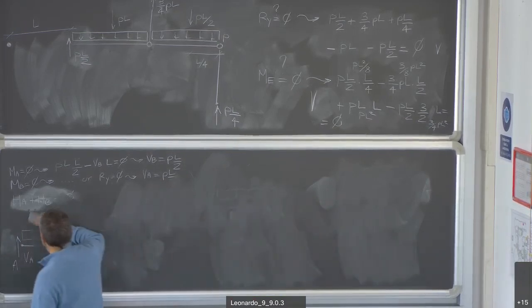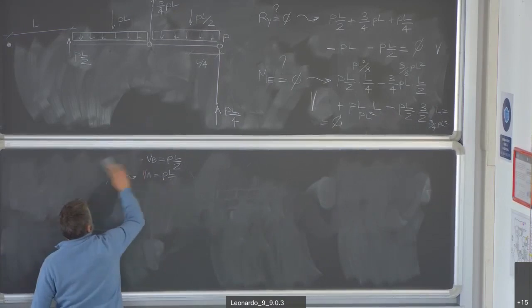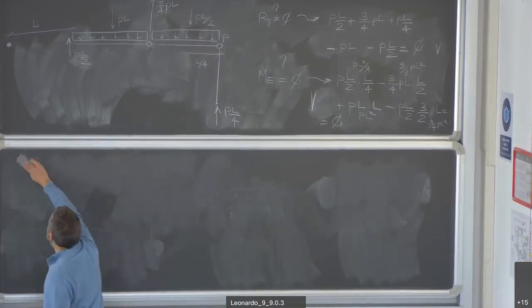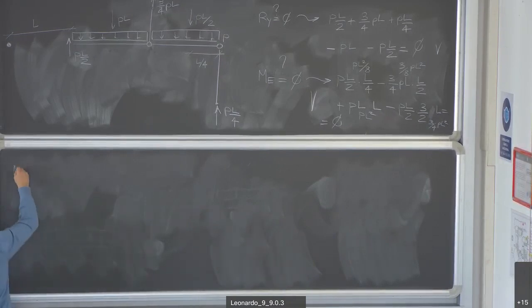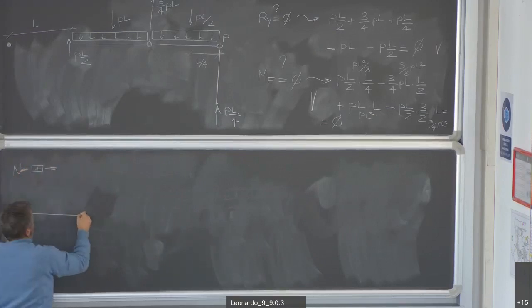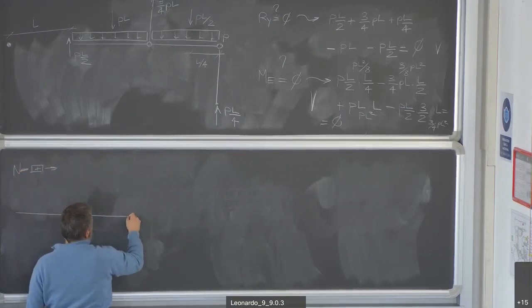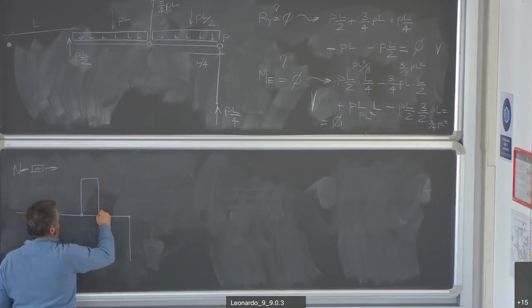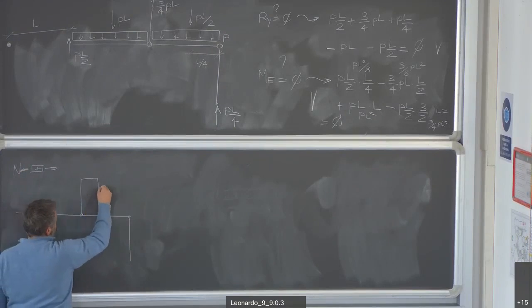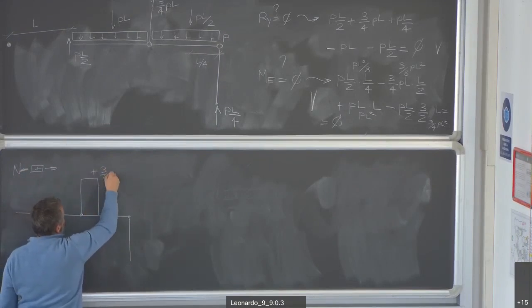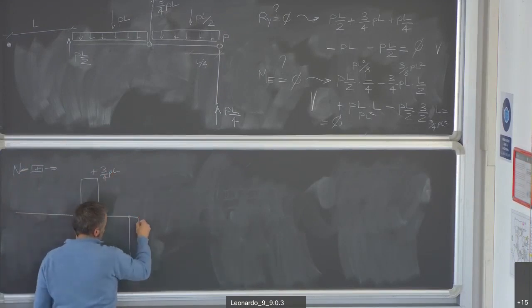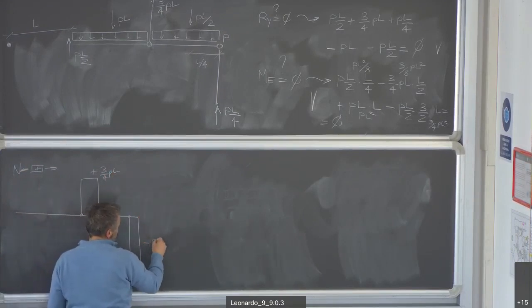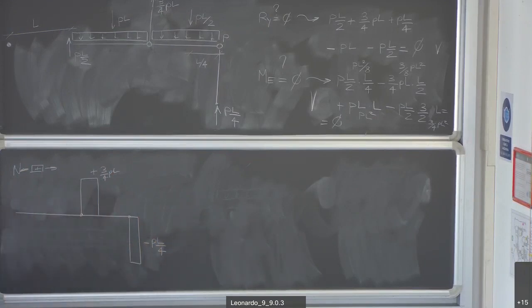So now, diagram of the internal force. What will it be? I assume positive tension, so rectangle on the tie, the value is plus 3/4 PL. Negative on the column, minus PL divided by 4. The ratio between the two is 3.